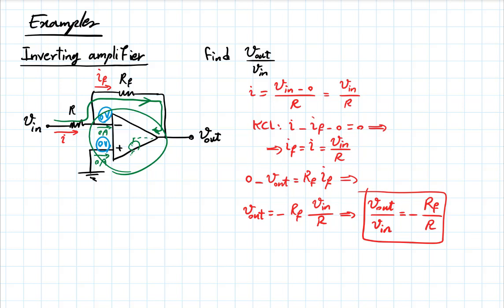And so you will see that depending on what you connect at the output of the op-amp, you might be delivering more power to what you have at the output than you have given it input power from your input signal. That extra power comes from the supply voltage, the supply sources. And so the op-amp is an active element. It's something that you have turned on, that it can actually add power to your circuit.